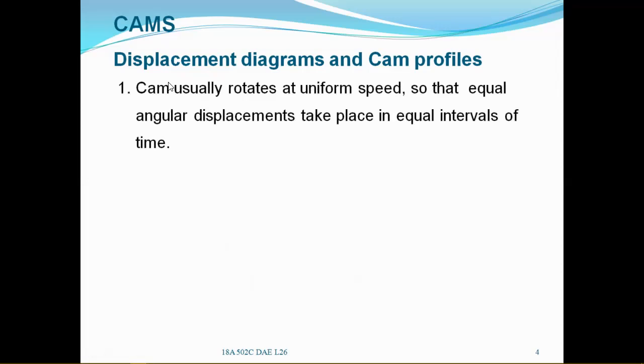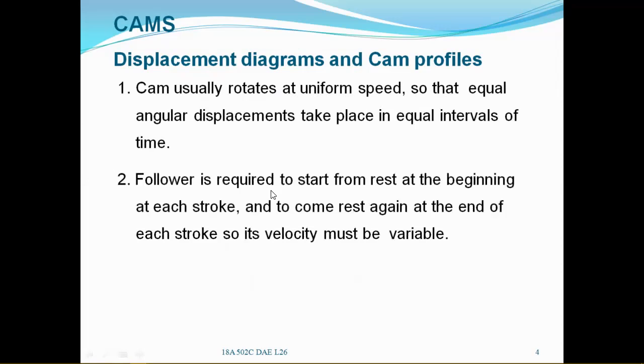Now here in these displacement diagrams and cam profiles, the cam usually rotates at uniform speed, as we are aware, so that the angular displacement takes place in equal intervals of time. The follower is required to start from rest at the beginning of each stroke and to come to rest again at the end of each stroke, so its velocity must be variable.